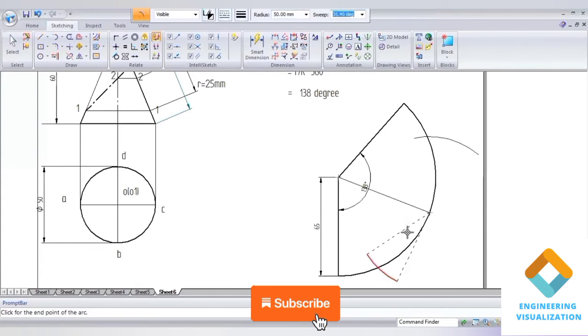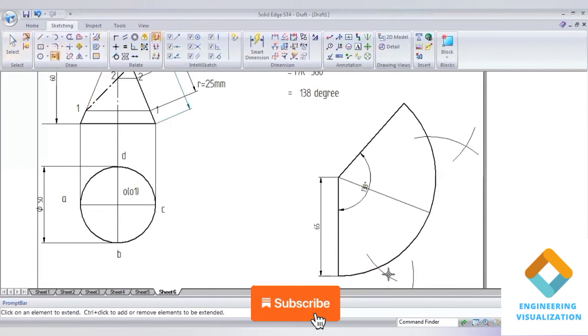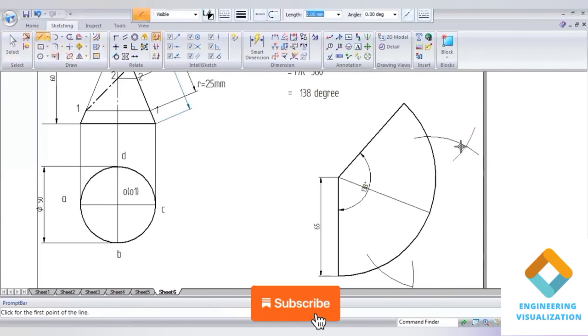Cut the arc. Again, from that extreme point you consider the radius 50 and cut the arc. Here also you can consider a radius of 50 and cut the arc. We can extend these two arcs. Yes, now you can see that clearly. Now you can join these points with a straight line to that point here, so that it will be divided into exactly 4 equal parts.